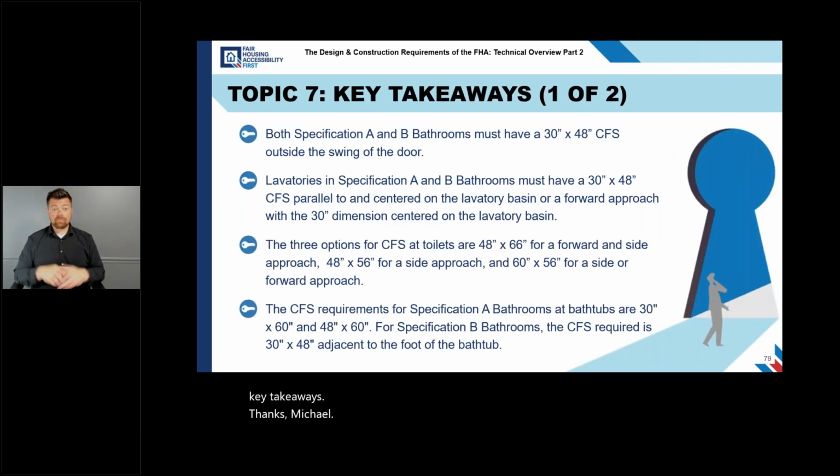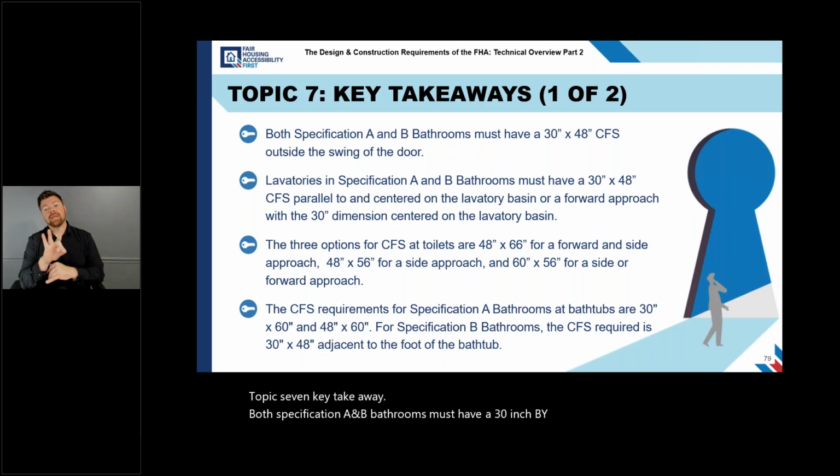Topic 7, key takeaways. Both specification A and B bathrooms must have a 30-inch by 48-inch clear floor space outside the swing of the door.